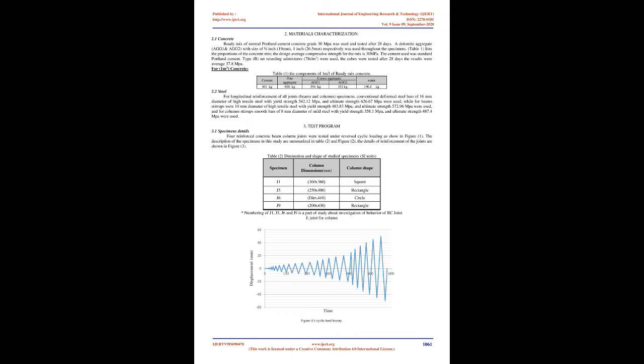Flora Faleschini et al. studied the influence of using electric arc furnace, EAF, slag concrete in performance of reinforced beam column joints using 3 real scale joints under quasi-static cyclic loading. Study was carried out to understand the effects of column axial load, beam longitudinal reinforcement bar amount and column transverse reinforcement ratio. Results indicate that, in all the analyzed cases, the seismic performance of the joints made with EAF slag concrete is better than with conventional material.